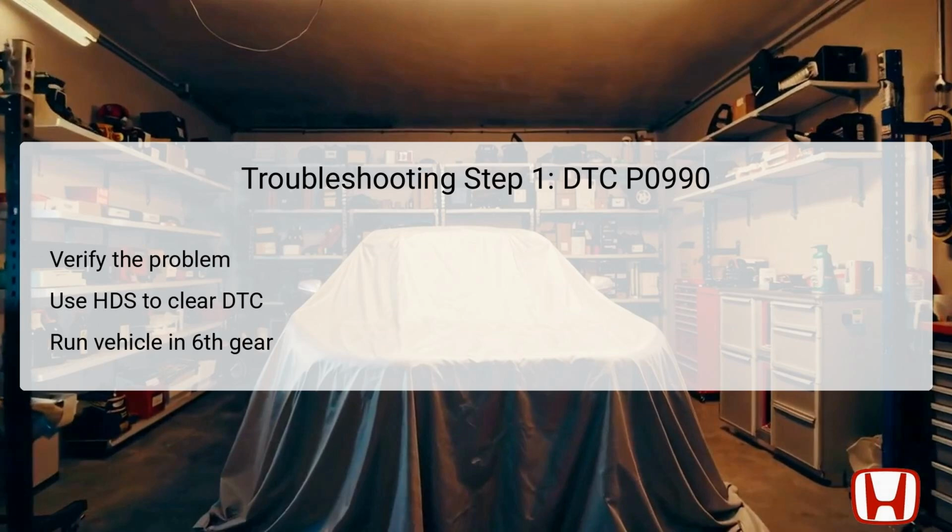Once cleared, securely raise the vehicle to ensure that all 4 wheels can rotate freely, and start the engine while disabling the Vehicle Stability Assist (VSA) by pressing the VSA off button. This may be critical if the vehicle is moving at speeds exceeding 31 miles per hour, 50 kilometers per hour, as it enters maintenance mode.